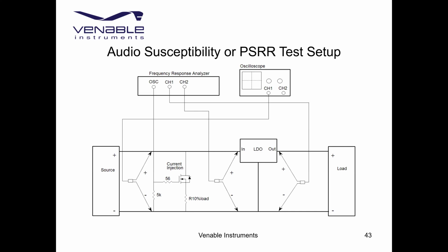Some people use a voltage instead. If you do 80 watts into a half ohm load, I believe it's like 6.32 volts RMS power injection level. A lot of it depends on how much power your power amplifier can deliver. The ones we use can put out about 500 watts. I don't think they would have any problem with that test. It's, are you injecting too much? They're very vague on that. So I guess that wraps it up.